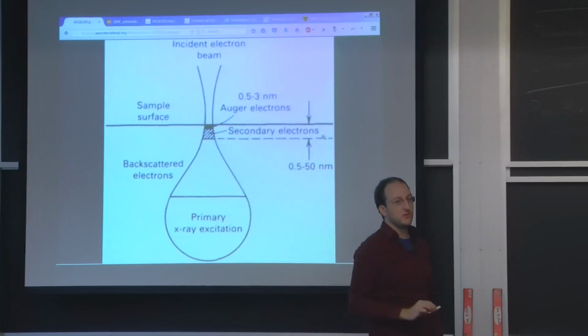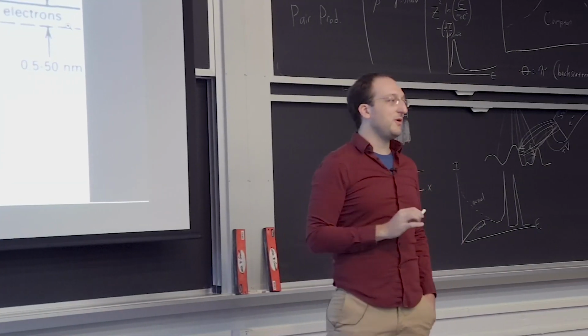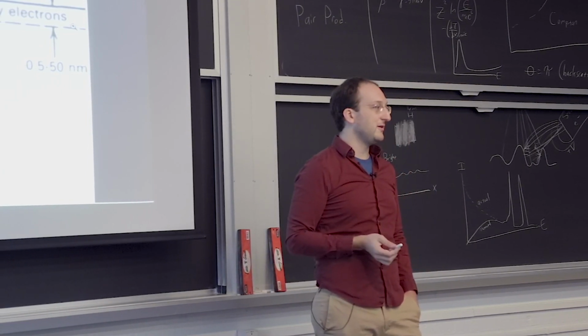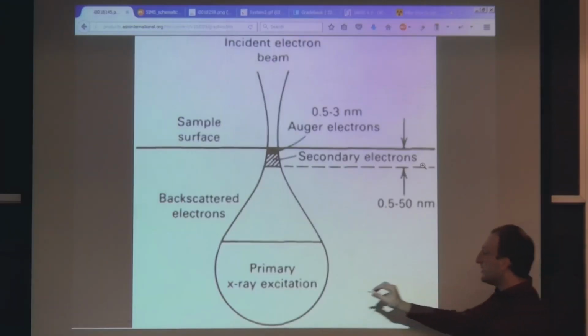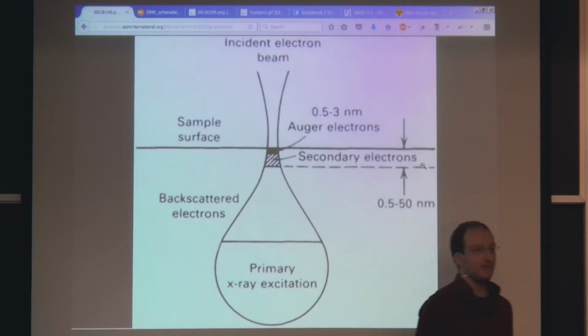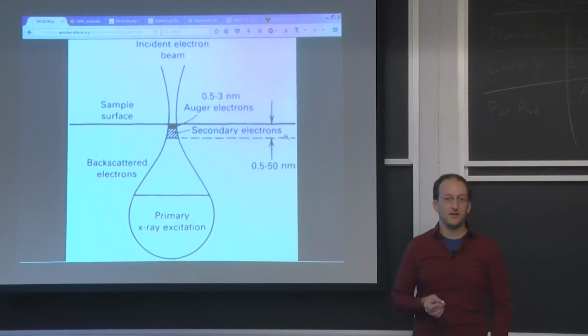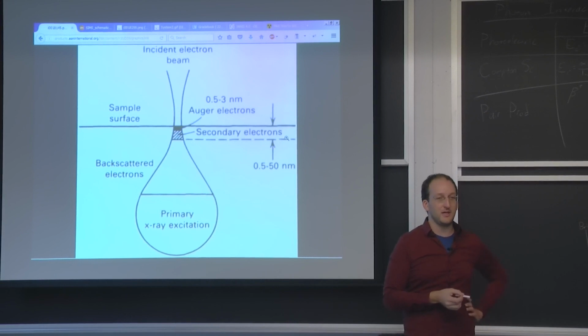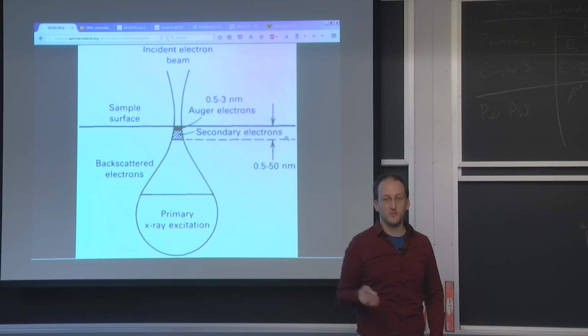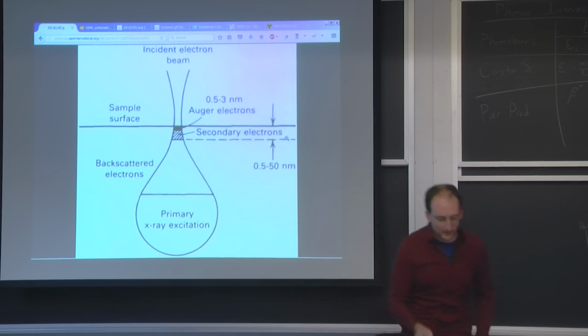So as you change your electron beam energy, you might see your elemental composition appear to change when you know it's really not. That's because where the X-rays are being generated changes, and proportionally more of the low energy ones get self-shielded by your material. So you actually have to correct for that and input your beam energy into the EDX analyzer so it knows how to correct for this. But with the understanding I've been giving you in this class, you can understand why you can get screwed up, and why we have to have all these correction factors, which I think is pretty neat.